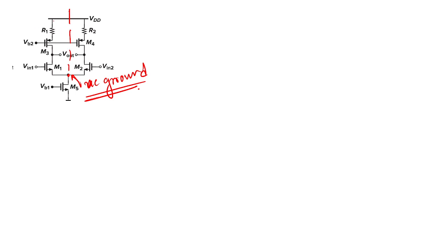Now our task is to find the output impedance of this structure. This is a common structure, like for NMOS. I am showing the calculation for NMOS; for both NMOS and PMOS, the calculation will be the same. Suppose this is a circuit and we are looking in from the drain.